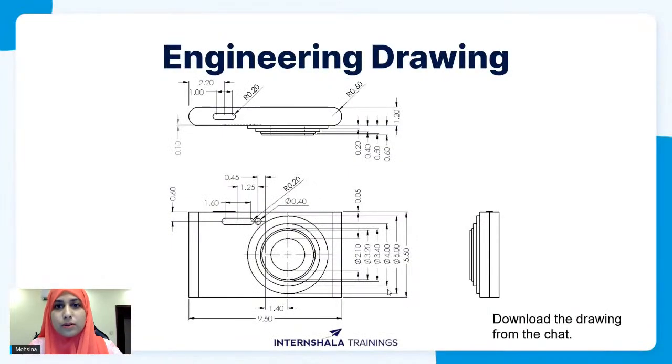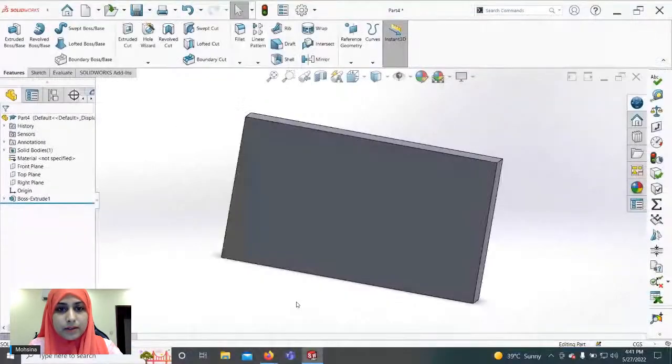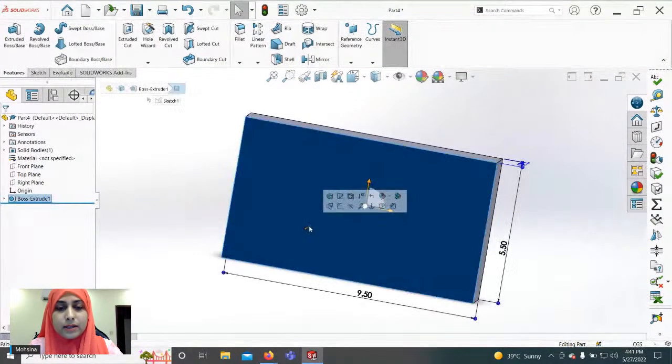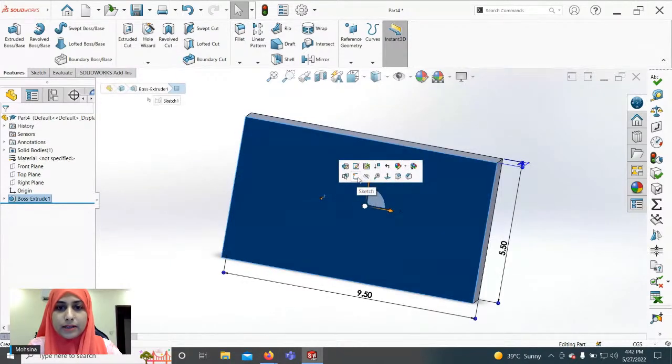Now let's go to the drawing again. The next step would be to create this circular lens part. Let's go back, click on this face. The first sketch that we created was created on front plane, but as we go on and start extruding things, every flat surface or a face becomes a plane and we can create another sketch on it. So click on it, and from the pop-up, you can click on sketch,